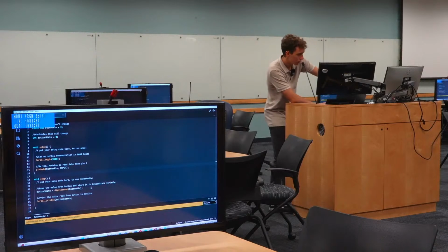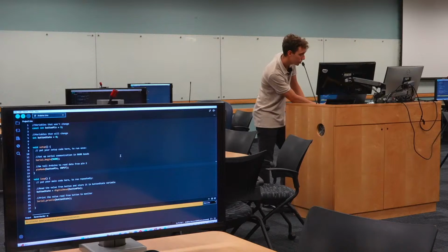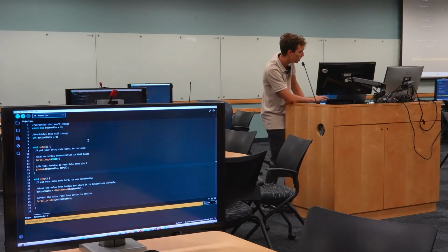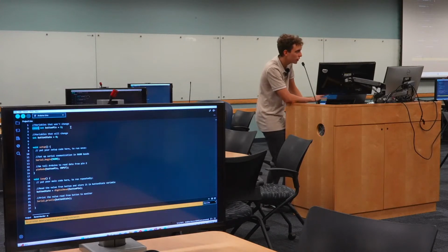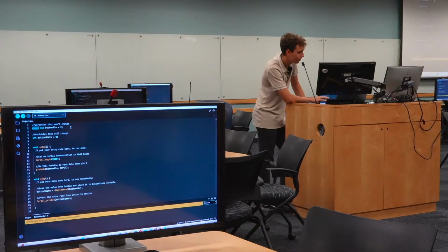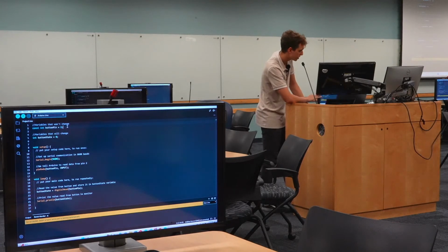All right, guys, so explaining what's going on in the code. Remember that for all the Arduino sketches, on the top, we're going to define all the variables that we're going to use, both those that are going to change and those that are going to be constant. For C++ notation, we have here a new keyword, which is const, which is basically for us to know and for future developers that might get the same code base to keep developing upon it. So you're saying that button pin is never going to change, and that's actually what's going to happen. It's never going to change.